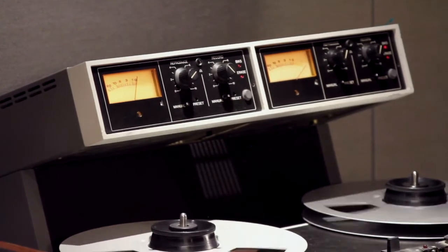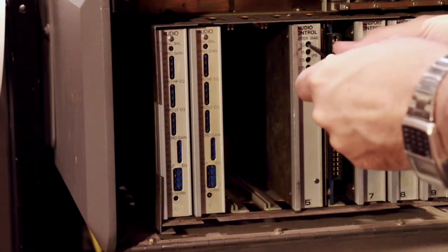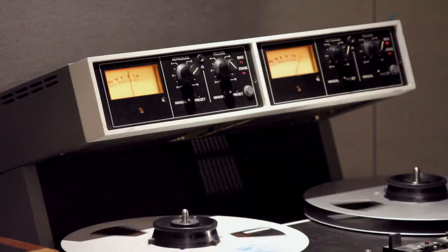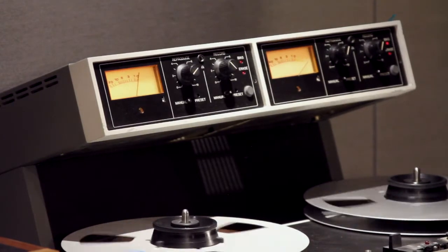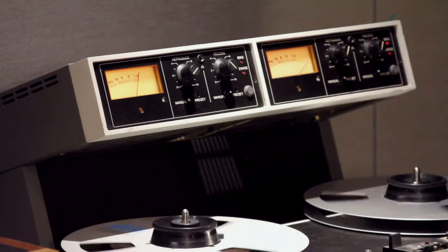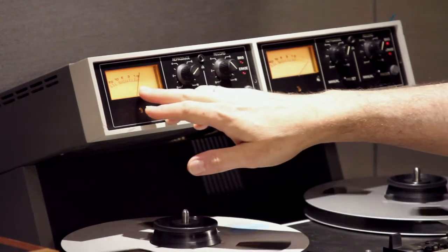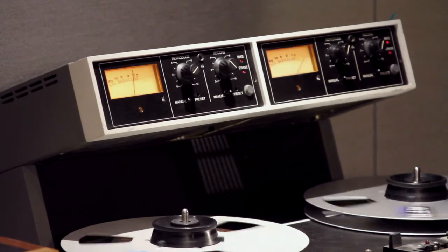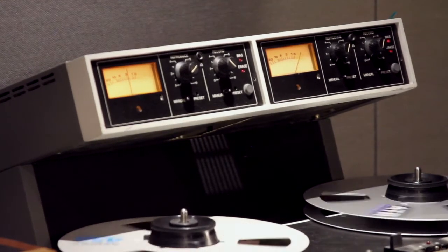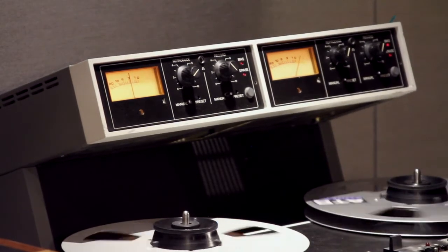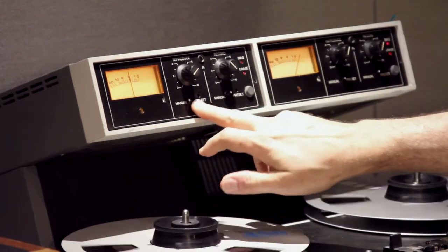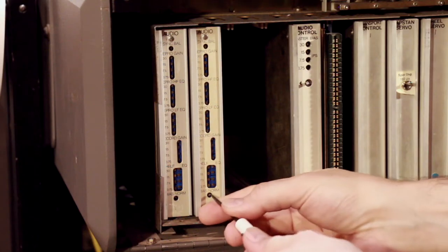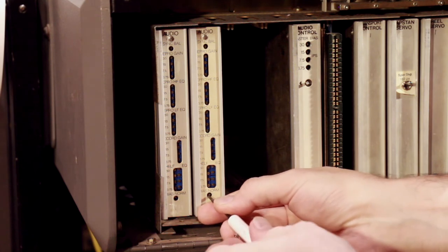And here you can see I've found the peak. If I increase the bias, the signal drops. If I decrease the bias from that point, the signal drops. So I'm going to start increasing the bias from this point until we get to minus 3 dB, which is the point that we've found at 20 kilohertz corresponds to lowest noise and distortion on this machine. So I am now calibrated on the left side. So I'll put this machine back into the calibrated output, and I'll do the same on the right, but I'll use the individual channel trim pot here.